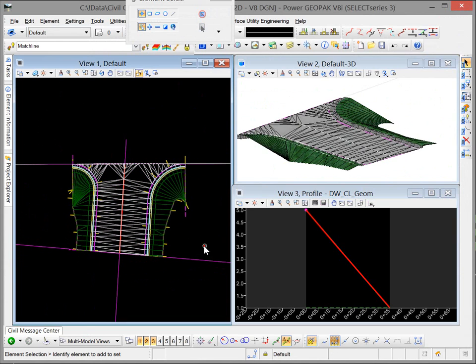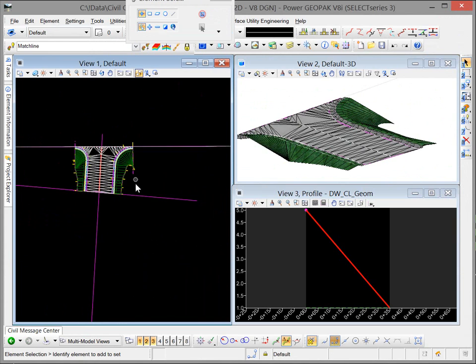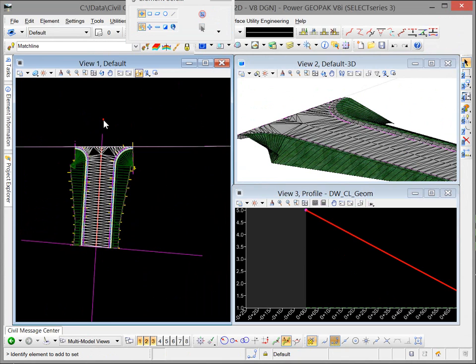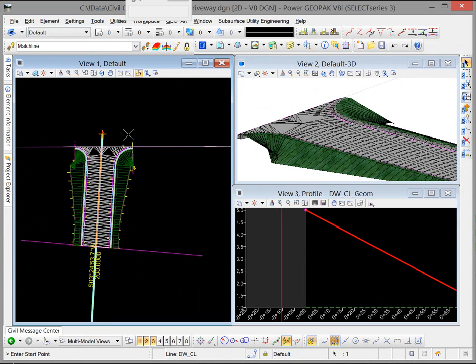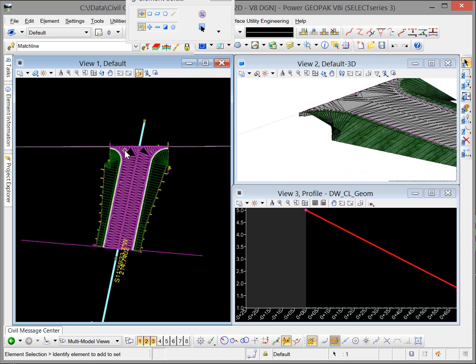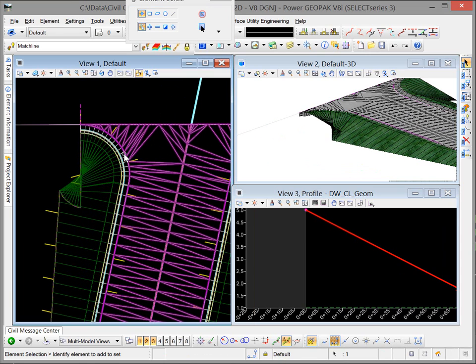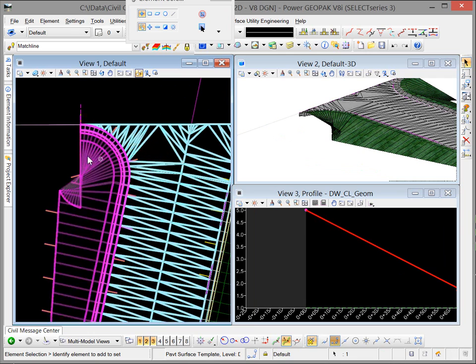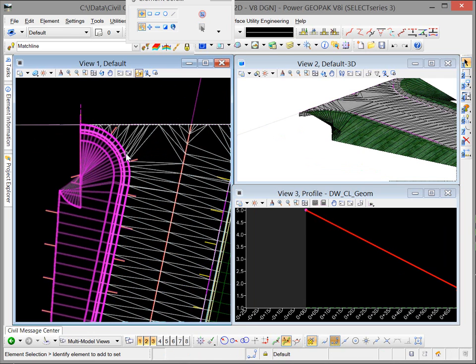And again, it's always a good idea to test it. I can come in here, drag this line down, wiggle my geometry. I should see things heal properly. It doesn't really matter what I try, I should not be able to break it. And so I'm just going to set this radius to something a little bit bigger here. So we'll pick that radius, which is here. Let's set that to 15 as well.